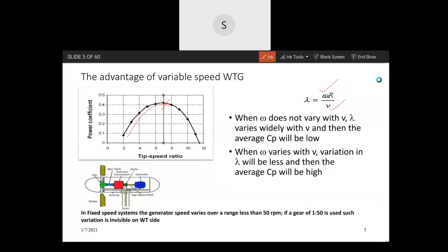They are basically induction machines. You know that in an induction machine, especially the squirrel cage induction machine, the slip variation or the speed variation from no load to full load is very small. Only 3 to 5% slip will be there. If you are considering very large machines, it is still smaller. But by design, we can increase it to some extent. Otherwise, the slip is small. For that reason, the variation in the speed is less.